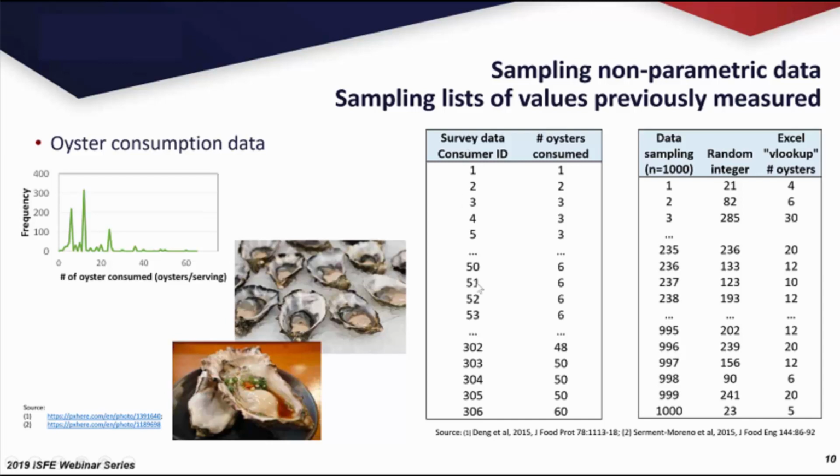If I want to do a probabilistic design, I still want to meet 180 days, now with a confidence of 90%, so now the failure risk is 10%. This would be the film permeance you need to request from your packaging supplier. So a 10% reduction in the moisture that is allowed to cross the film. Okay?